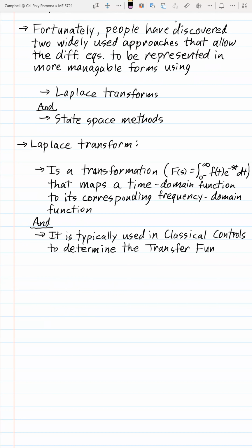So even though we could have multiple input, multiple output systems, even in classical controls, and we could work to try to analyze what was going on, we could only write a transfer function between one input and one output, and in a lot of cases analyzed in a classical controls class. Not that it really reflected reality, but the reason we can call it a system is because you really did only have one input and one output, in which case the system itself was all captured by the input, the output, and the dynamic behavior of the system itself.